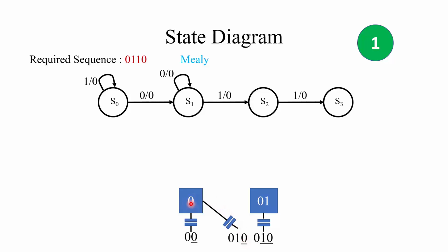Okay, if this turns out to be a match, we can go to state 1 and we can make a state transition to S1. Otherwise, if this also doesn't match, then we'll have to reset to the reset state. So in this case, you can see it turns out to be a match in our particular example. This means the next state from S2 will be S1 when the input is 0, and we'll keep our output low as well.